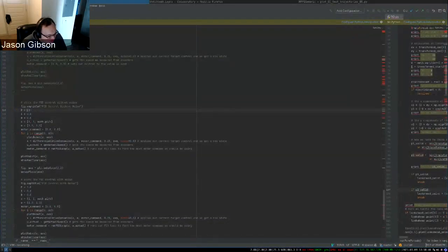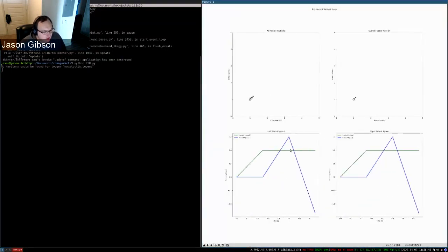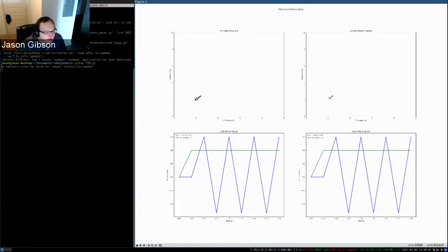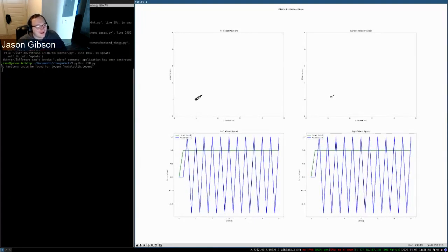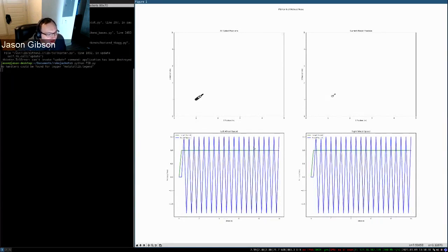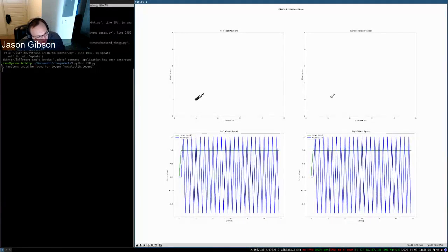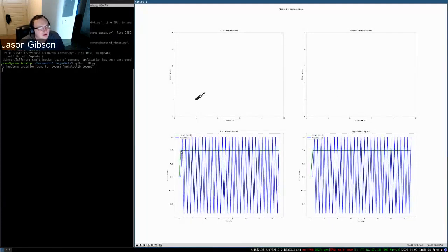I'm going to go really high, something like 20. So if we do a P of 20, what you'll probably see is, I don't even know if it'll handle it. Yeah. So what you're actually looking at is friction being a problem, but how I implemented physics here. Essentially, what you're seeing is the controller is bouncing around. It's not converging to anything, it's just bouncing, and it's only doing this because there's no noise in the world, and I implemented friction correctly.